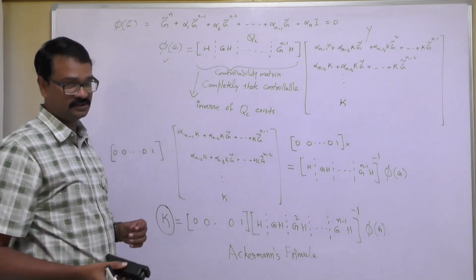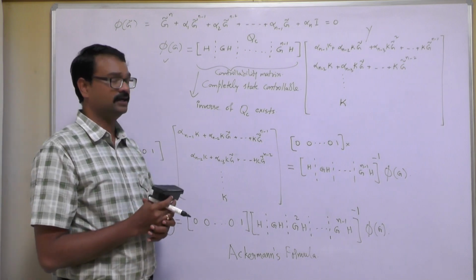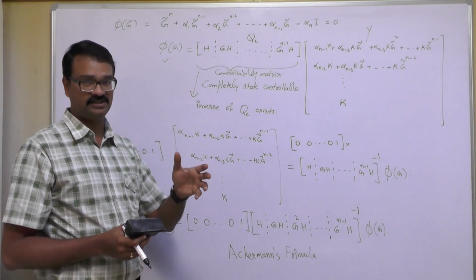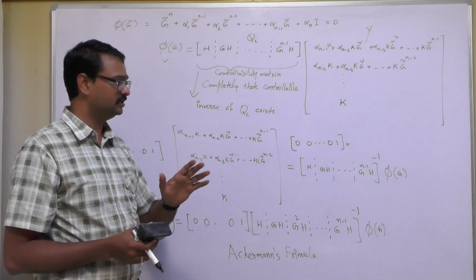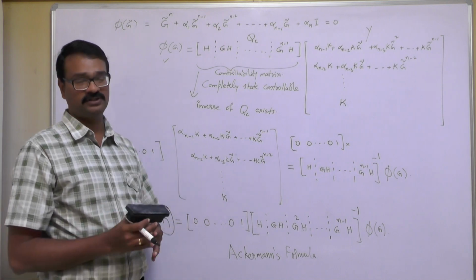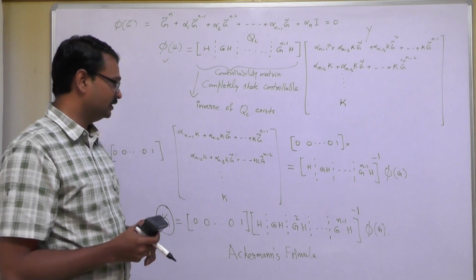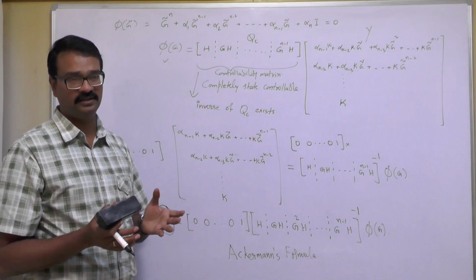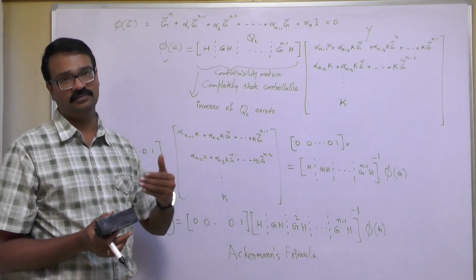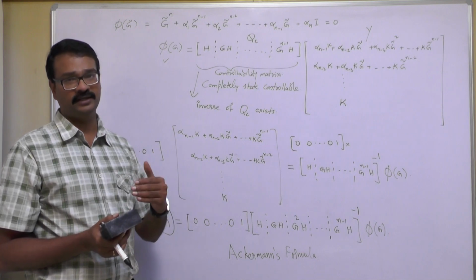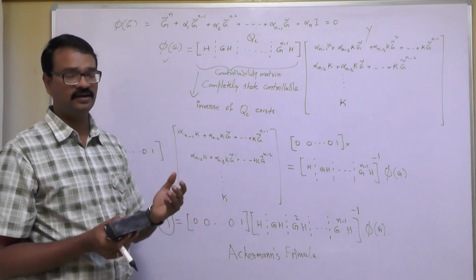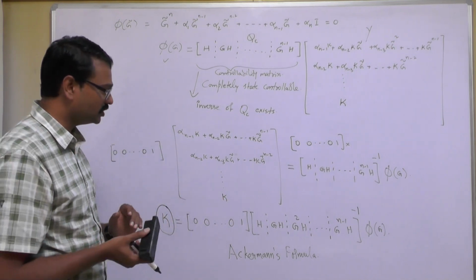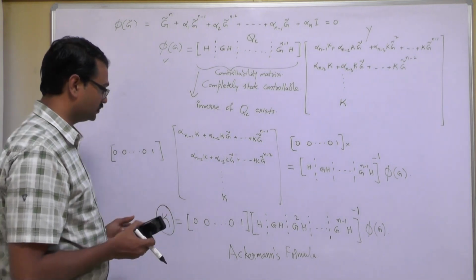You have many other methods, and we should understand that the matrix gain k is never unique for a given system. So it is the responsibility of the control system engineer to take a trade-off between all these different methods and see which gain matrix is better to reduce the error close to zero. The error that is obtained must be going to zero, which is a much faster response. You require a much faster response. Therefore, that is what is required in this